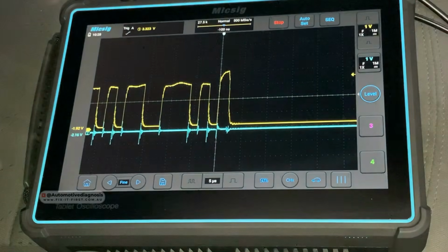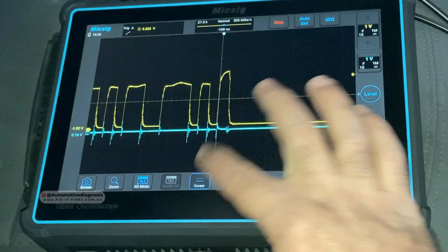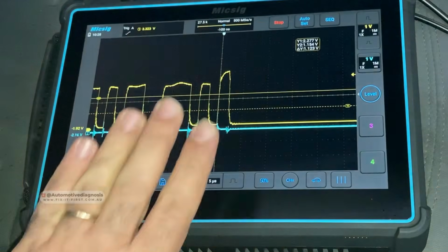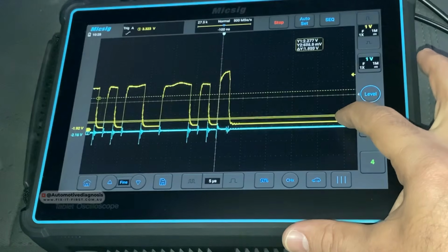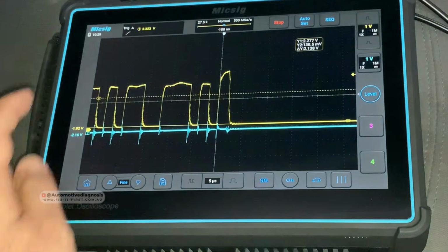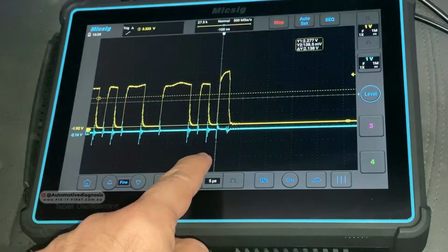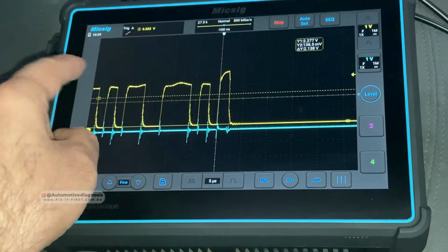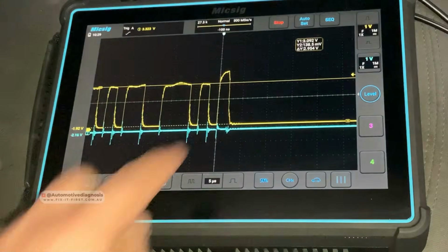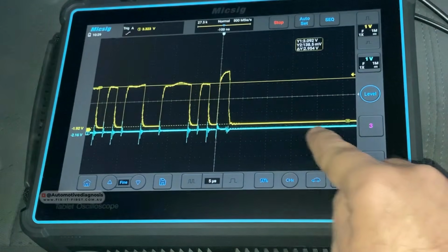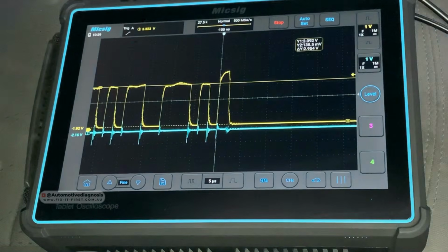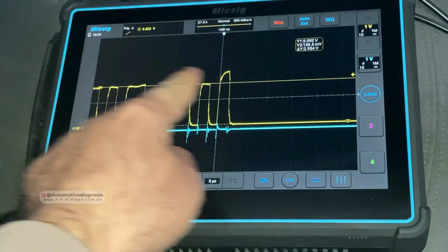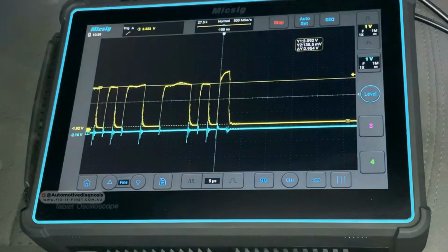And if we go for checking the voltage again, CAN low is showing us something very close to 0. But on the CAN high, see what we are getting right now. Again, remember that I made the short ground on CAN low, and it's affecting the CAN high as well. So you see the voltage already changed. At Y2 at the base, where we should have 2.5, we have something very close to 0, 138 millivolts. Up here, where we're supposed to have 3.5, we have almost 3 volts.